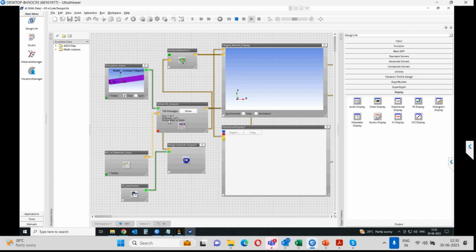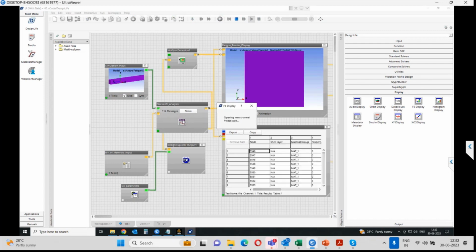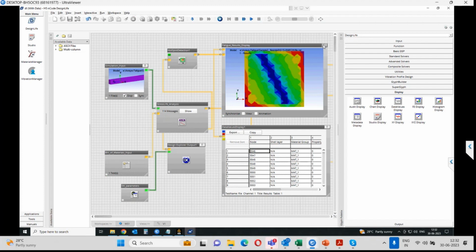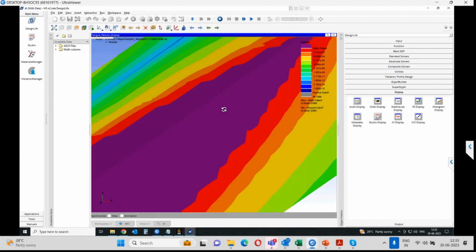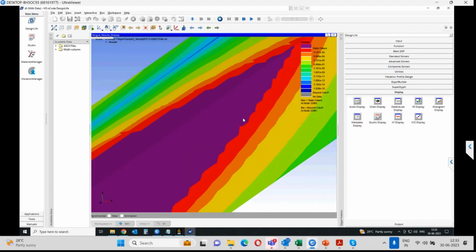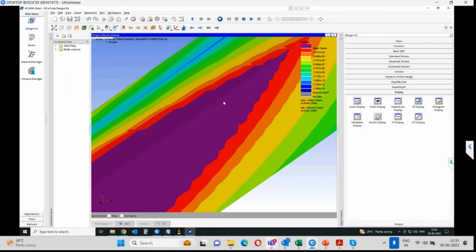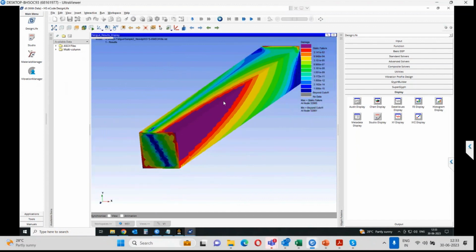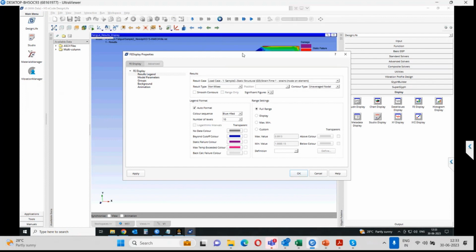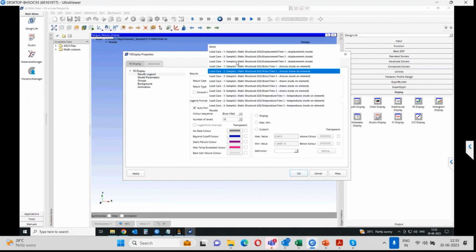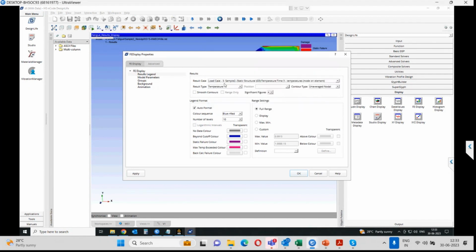You can see the 0 completed entities and other cases. So just maximize this, hold the control button, where you can rotate and see. There are different post-processing options available. Because of the time constraint, I'm just rushing through this. Here you can see the damage levels, the static failures, and also you can put a band. Double click on this. You will be able to see the results for different load cycles, depending on what load cycle you want to see, or load cases, the damage levels you want to evaluate.